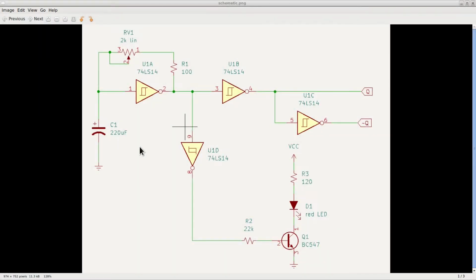An important thing to remember when using a Schmidt trigger inverter as an oscillator is that when we use TTL logic for them, we are limited to feedback resistors of up to about 2K. Bigger resistors cause a voltage drop too high, and the circuit could not oscillate at all. And so, because of the relatively small resistance, when using TTL logic, we need to use big capacitors when we need a very long period of the output signal.